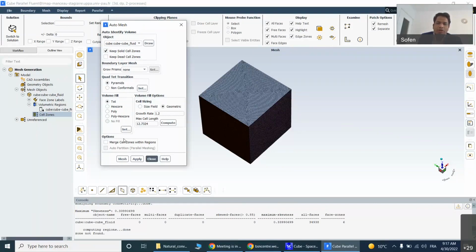But if you come close to the vicinity of the solid wall, you can no longer discard the presence of molecular viscosity. Close to the wall, the molecular viscosity predominates, and that is called the viscous sublayer, where the viscosity effect cannot be neglected. Then above the viscous sublayer there is a buffer layer, then a log layer, then a defect layer, a lot of things. Theoretically, hopefully you have gone through it, or Professor Andy Chan will cover those things about turbulent flow near the solid surface.